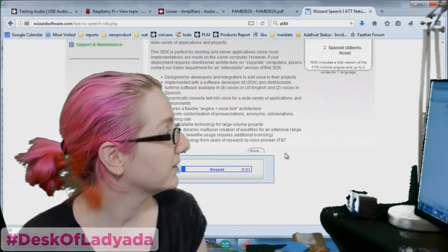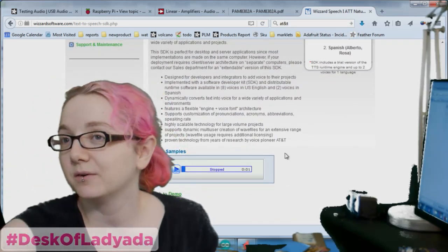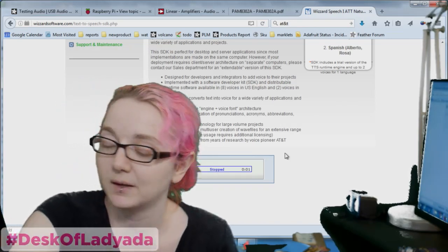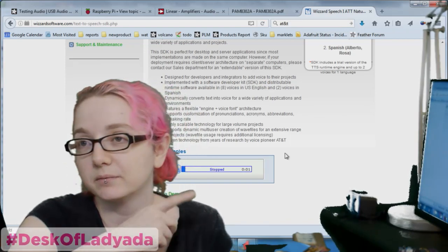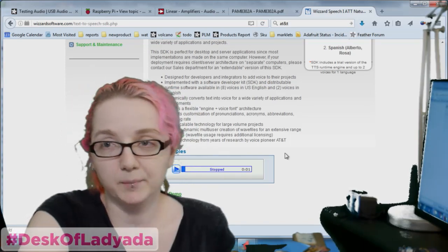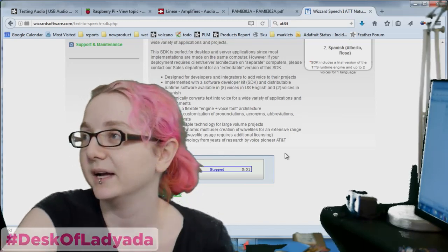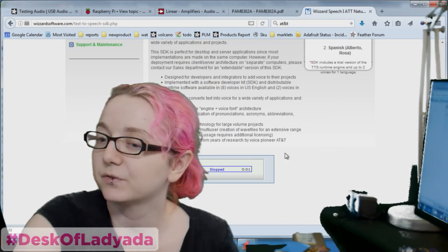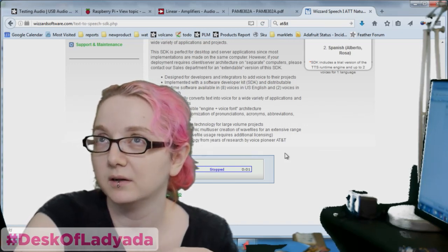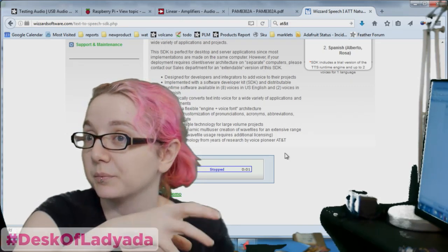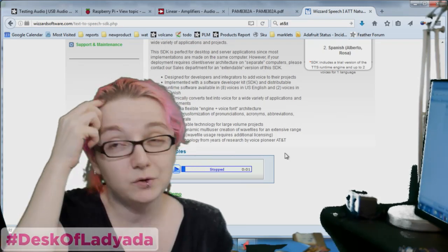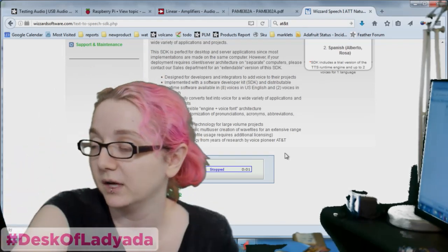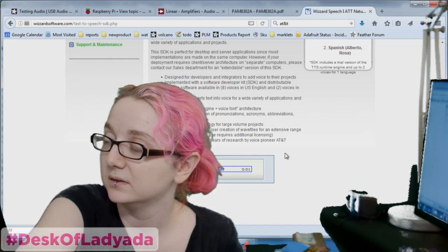Well, you know, that's how it goes. It used to be you could just generate a WAV file for you, and you could download it and then load it. So on the Wave Shield, that's how I generated some examples. So I'll probably end up finding something similar to this, putting it on my iPod, and then having it say pi or a couple of text to speech type voices, and then the Circuit Playground has enough storage that I can generate those waves and then store them in the Circuit Playground itself on the SPI flash. Like 2 megabytes of 8 kilohertz audio is quite a few seconds, so I can have a wide range of spoken words.